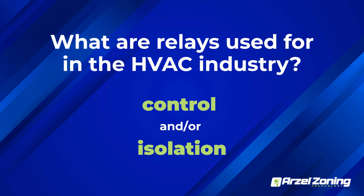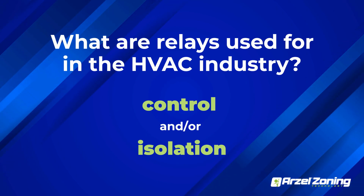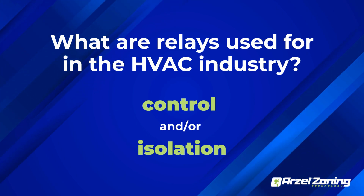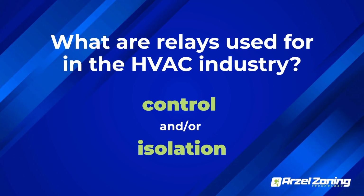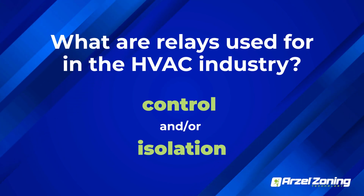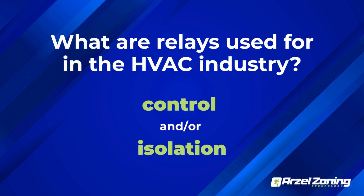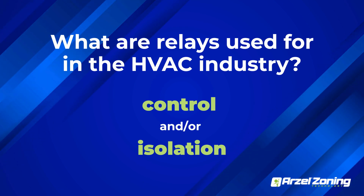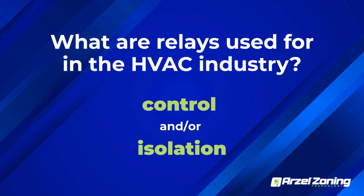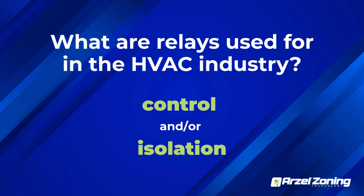On the isolation side of things, you have a humidifier or the Arzel panel. Perfect example. The Arzel panel has its own transformer. The transformer in the Arzel panel powers all your thermostats. However, your furnace has its own transformer as well. We cannot tie those two transformers together, so we have a bank of relays on the Arzel board that provide you your isolation.